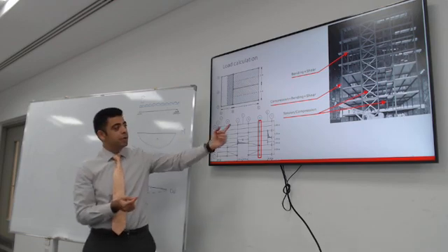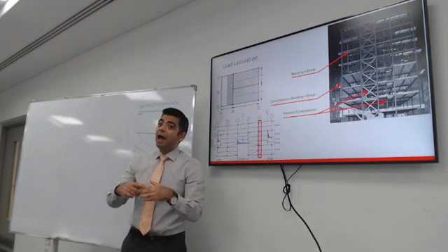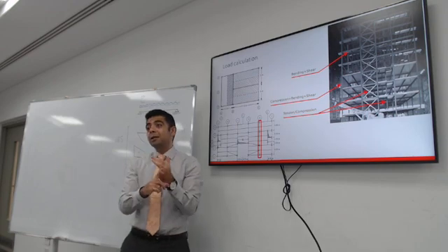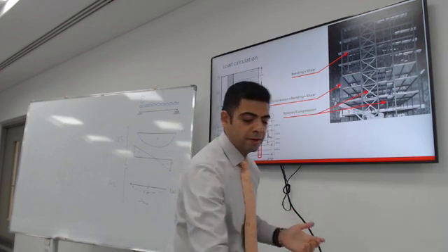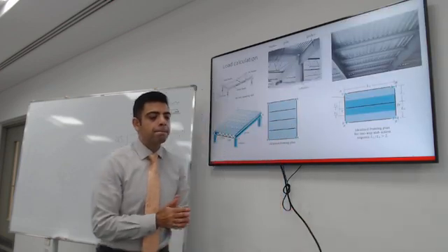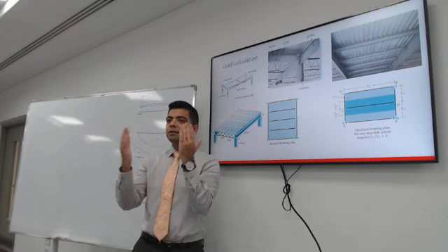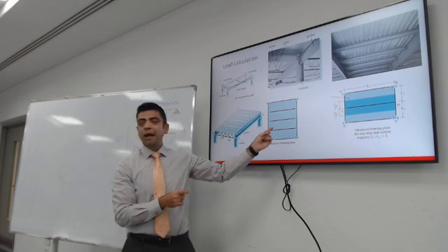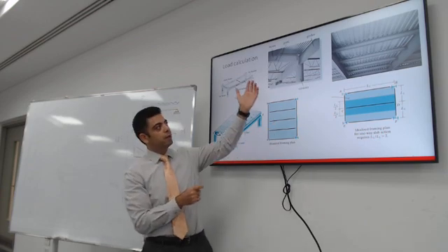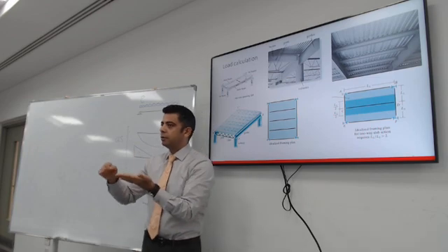I asked you, get the location of the columns, put the location of the beams, and next step, I already asked you, get dead load and live load on the beams. So that's obviously the first step. You will have to connect very closely how the building is built with your analysis. So if the building is built differently, you will have to consider that in how you calculate the load.